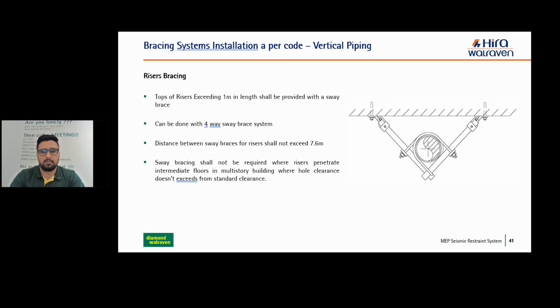Risers mainly, when we talk about risers, there are a lot of standards, but it mainly depends on the actual application on the site. If the existing support is already installed and is well enough to sustain the seismic forces, then there should not be any requirement for additional bracing, because there are a lot of things: you have space constraints, you have enough support with the isolators for expansion and contraction, and sometimes we see requirements for bracing. If it is not applicable, then the riser designs depend on the normal support capacity. If it is enough, then no need for additional brace.